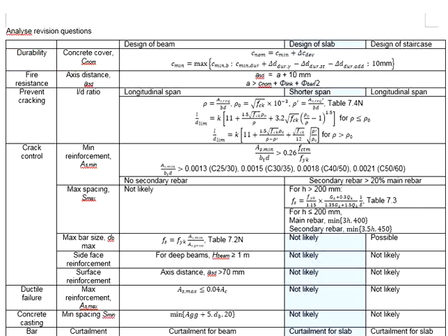You have reinforcement embedded inside the concrete, and there is a requirement of the nominal concrete cover, which serves as the protective layer to the steel reinforcement, protecting the steel reinforcement from corrosion due to the moisture, carbonation, chloride attack, sulfur attack, and other environmental deterioration agents.